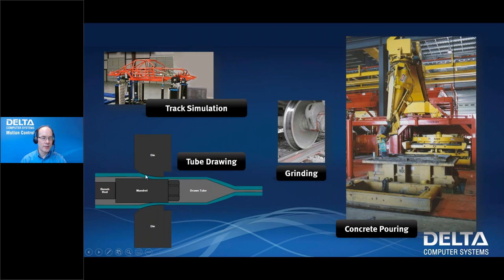Tube drawing: down here, we have a mandrel and a die that we use to move up and down and make varying thicknesses of the tube. Then this tube is put in a hydroforming press and squeezed with a lot of water. It expands into a shape and comes out, and now it can be like the frame rail of an F-150 pickup.